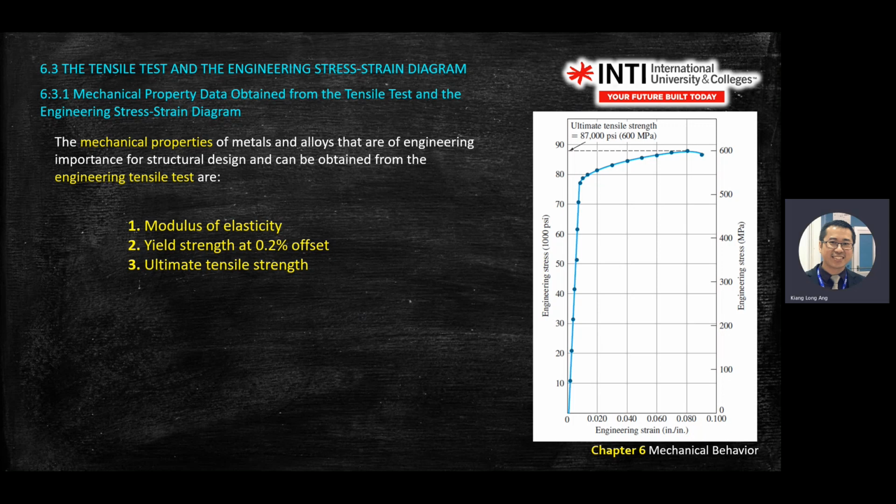For example, the lift cable. It gives you like 20 people inside the lift, a maximum kilogram there. That one is under a safety factor or so. But where they get that value is from the ultimate tensile strength. For example, the cable is able to withstand 600 megapascal. But to be safe, maybe they divide by 4, maybe divide by 2. Then it's a safety factor. So maybe divide by 2, you get 300 megapascal. Then you convert to layman's terms. 600 divided by adults, maybe 80. So you get so many adults inside the lift.